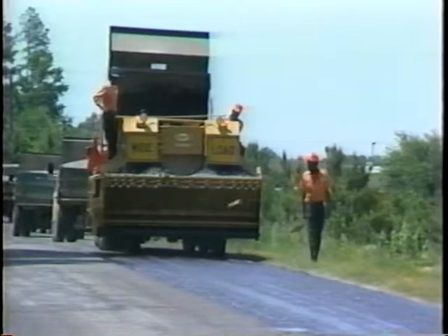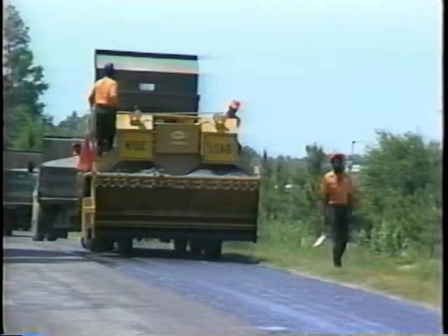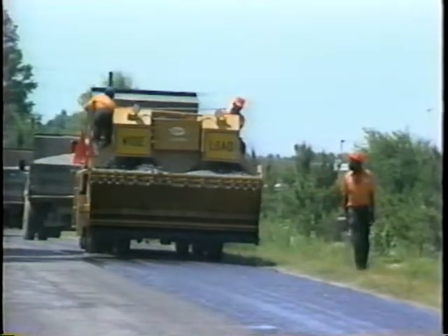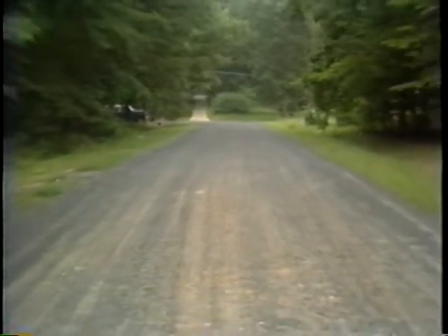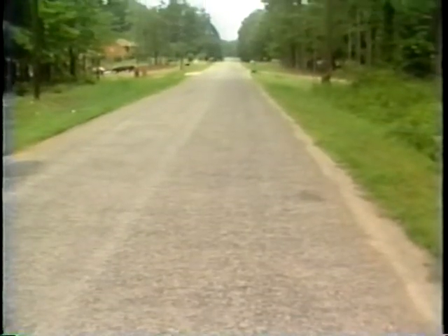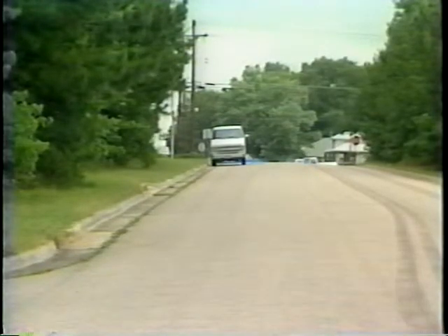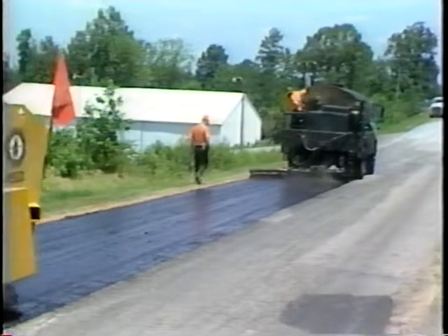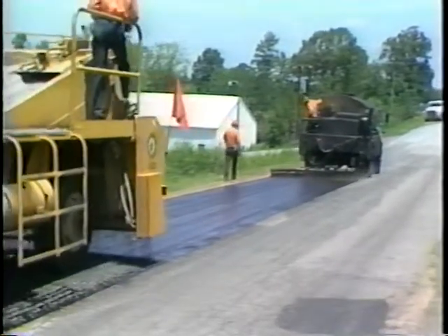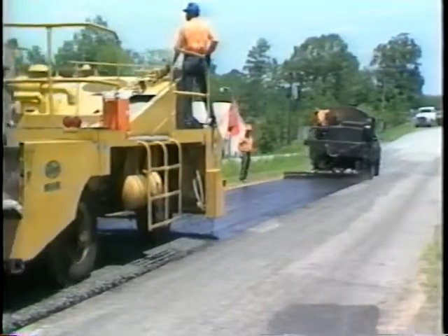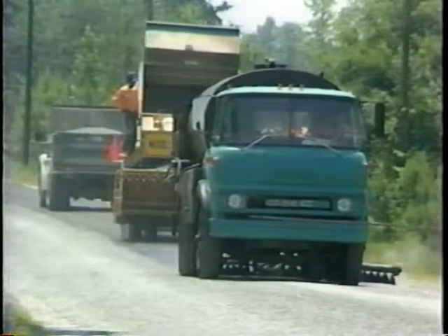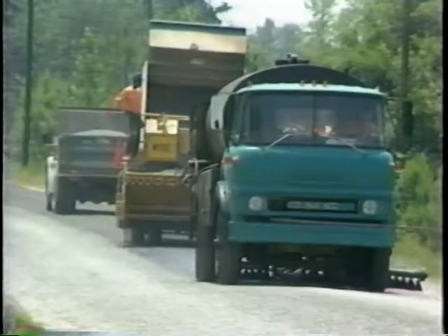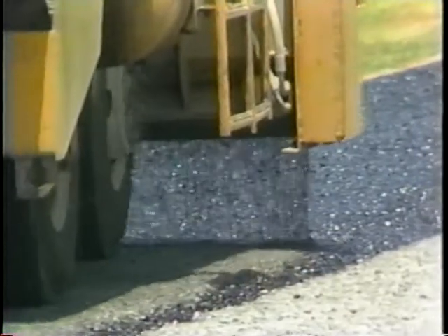The purpose of an asphalt chip seal is to provide a waterproof layer and a skid-resistant surface. A chip seal can be applied to an aggregate base, a previous surface treatment, or a plant mix surface. Asphalt chip seals can be single or multiple layers. A single layer asphalt chip seal consists of a sprayed application of asphalt covered with a layer of aggregate of a uniform size. A multiple surface treatment consists of repeating the process, with the aggregate size becoming smaller with each application.